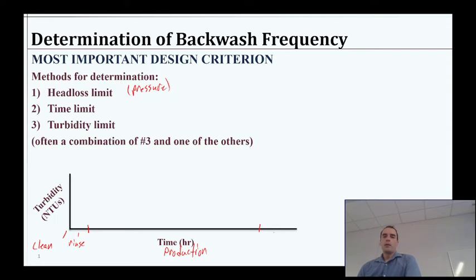Then we're going to stop and have a backwash. Now this might include an air purge as we saw. So I'll just add a little notch there. So air purge, which is really kind of tied to the backwash itself. But of course, we're not using any water during that time. So it's just sort of time that the filter's not doing anything. We're not consuming water during that moment. We're also not producing water. So then we'll have our backwash here at the end.